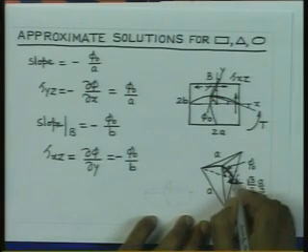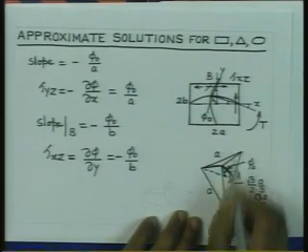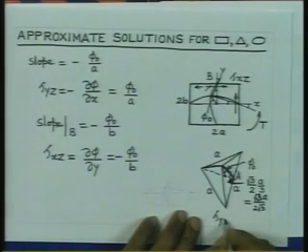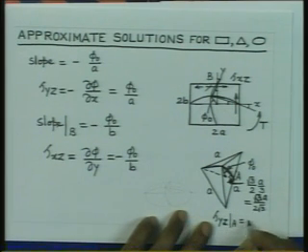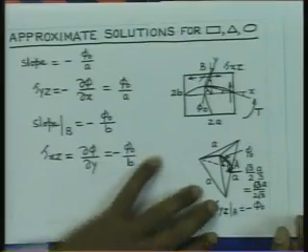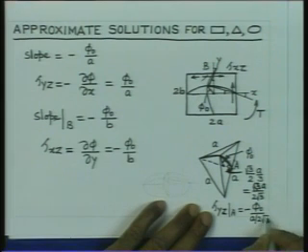And you can calculate now the stress parallel to this boundary at this point A. So, if you consider that this is your y direction, tau yz at A is minus phi 0 by the distance A by 2 into root 3.